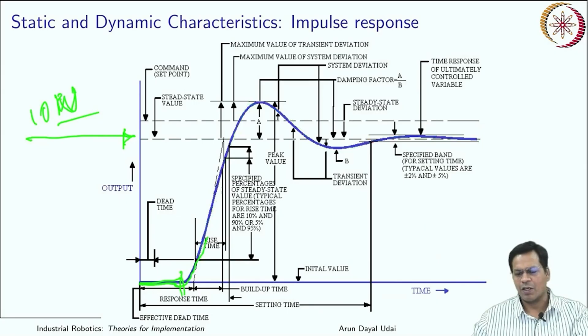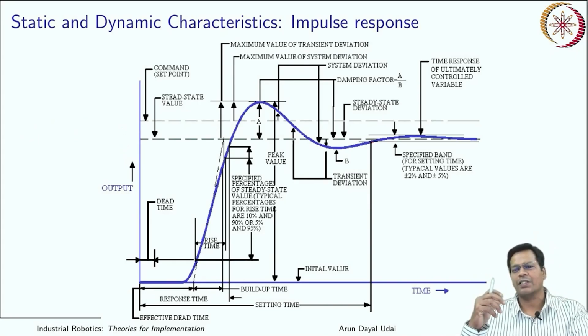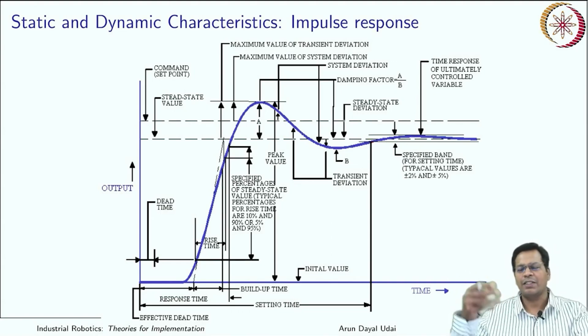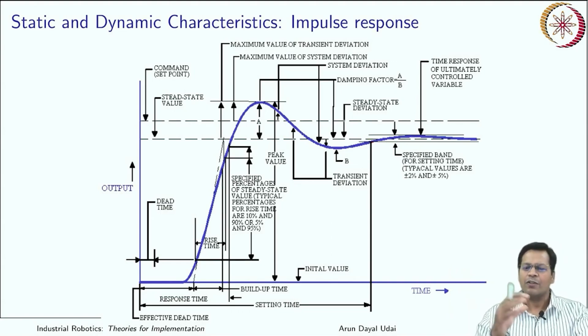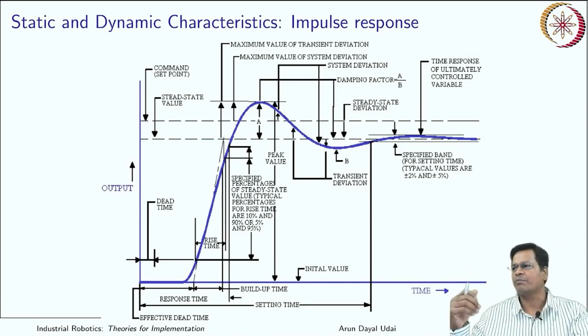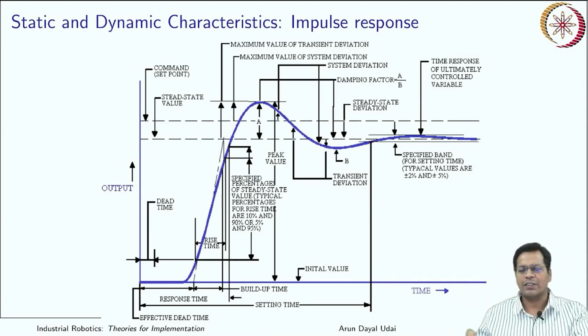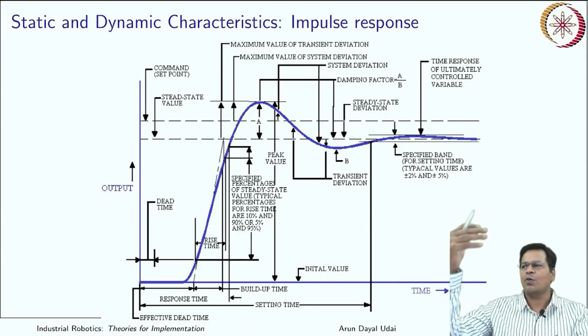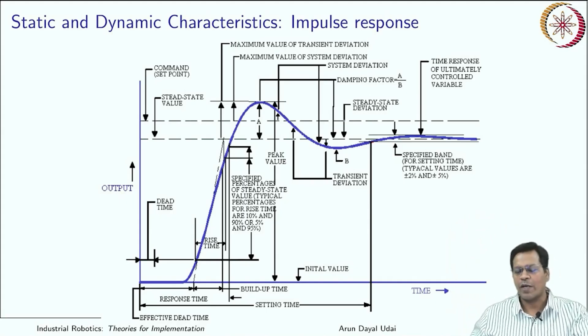At least in the case of an optical sensor, or an inductive or capacitive proximity sensor, you saw there are components. You had an oscillator circuit, a pickup circuit, then an ADC, then a digital converter, then a communication device. So there is sometimes a latency, or internal system behavior due to the electronic systems, which is something like a spring mass damper system. It takes some time, overshoots, comes back, and gives you a good value.